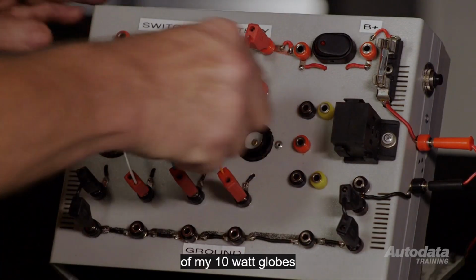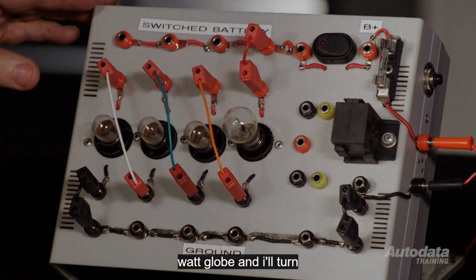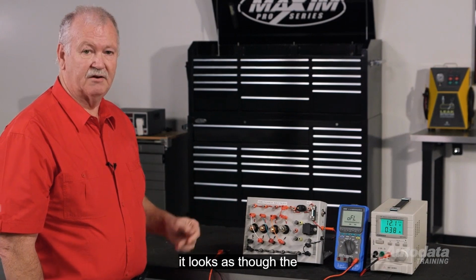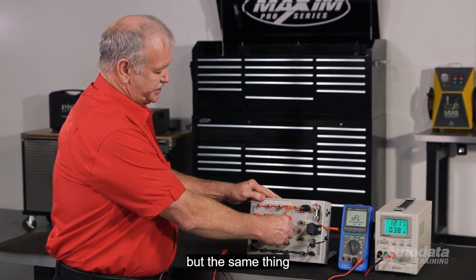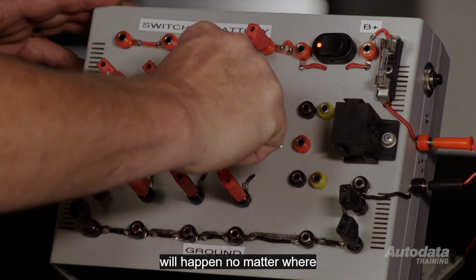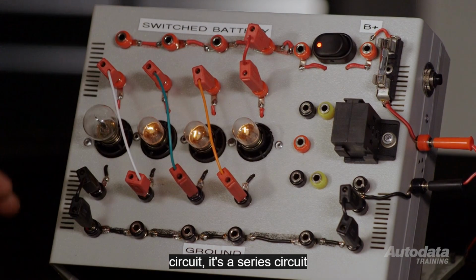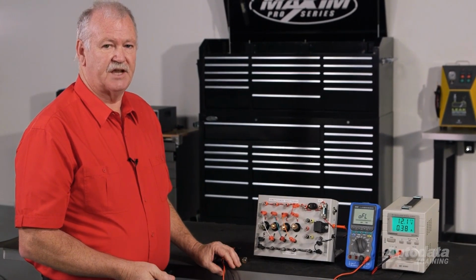What would happen if I changed one of the globes? I'll take out one of my 10 watt globes and put in a 21 watt globe. And I'll turn the circuit on. Straight away it looks as though the 21 watt globe doesn't work. But the same thing will happen no matter where I put it in the circuit. It's a series circuit. Does it follow the same rules?